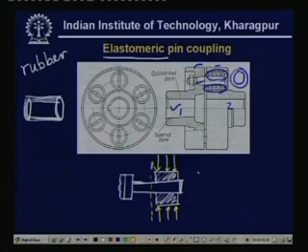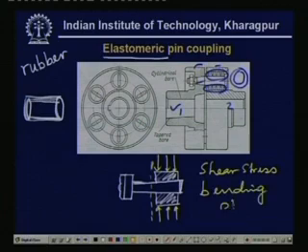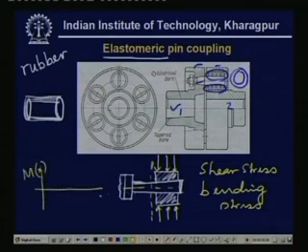Now you see that there will be shear stress in the bolt, as well as there will be bending stress. If you can draw the bending moment diagram, you can have some kind of bending moment diagram which is something like this. So it has some bending stress here, and there will be the shear stress.